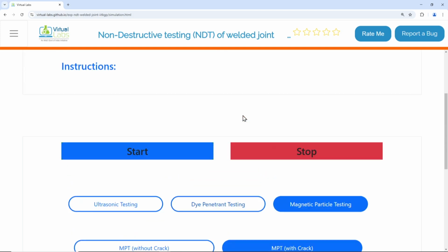If it is a destructive testing, for example, tensile test or hardness, we have to pick only some samples out of the 1000 pieces which are manufactured. If a tensile test is to be taken of the welding, then out of the 1000, for example, only 10 have to be picked, because those will not be usable later. So that is the difference between destructive and non-destructive testing.